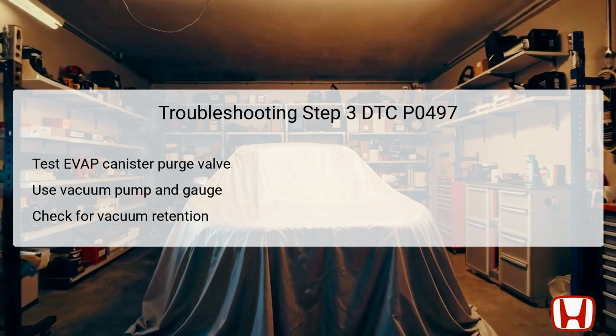turn the vehicle to the on mode to enable system functionality. Then, utilize the HDS to select the EVAP test. Navigate to the single solenoid section and initiate the testing process. By applying approximately 2 kilopascals of vacuum to the hose, check to see if it holds vacuum.